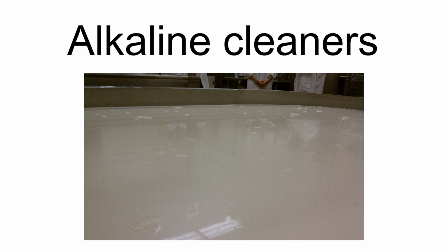The mechanism of alkaline cleaning action in proteins follows a three-step process. Gel formation: upon contact with the alkaline solution, the protein soil swells and forms a removable gel. Protein removal: the protein gel is removed through mass transfer, while the cleaning agent continues to diffuse through the soil, increasing gel formation. Decay stage: the protein gel has been eroded to the point where it is a thin deposit. Removal at this stage is governed by shear stress forces and mass transfer of the gel.